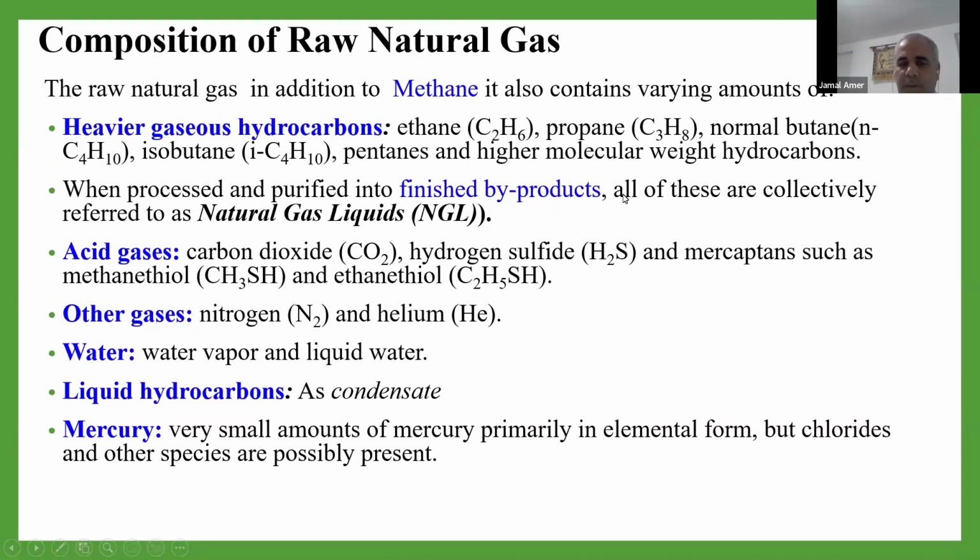The byproduct of the natural gas is formed as natural gas liquid, NGL. This NGL has another treatment by fractionation towers for further treatment. These fractionation towers are the demethanizer, deethanizer, and depropanizer.